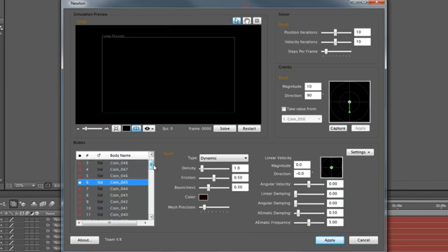Okay, now by default all bodies are dynamic, which is what we want, except for the floor, which needs to be static, not dead. If you set it to dead, it won't have any effect at all. So we need to set it to static, and that way it still has properties such as density, friction, and bounciness.